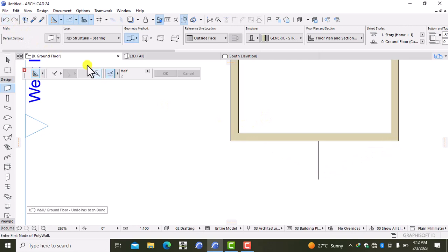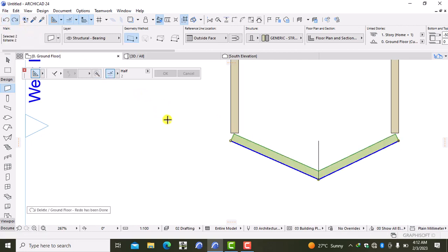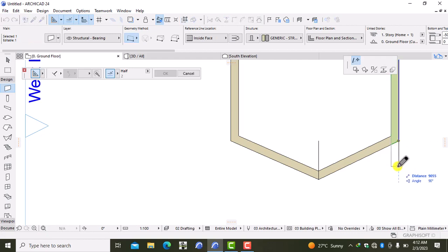Yeah. Okay. Once I've deleted it, I need to drag this particular wall. I just press shift to select the wall and move the node similar to this. Just press shift, drag the wall, and then I'm going to drag it further to a distance. This was originally around 8392, but I want to drag it to a distance of around 9300. Yeah, let's look at 9300 like that.